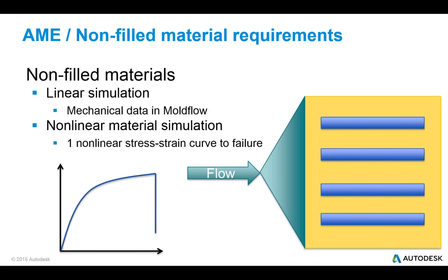Now, I know that there are non-filled materials that exhibit orthotropic material behavior, and MoldFlow does handle those types of materials, but we're disregarding those types of materials for now in Advanced Material Exchange. We're assuming isotropic material behavior with potential for expanding that in the future.